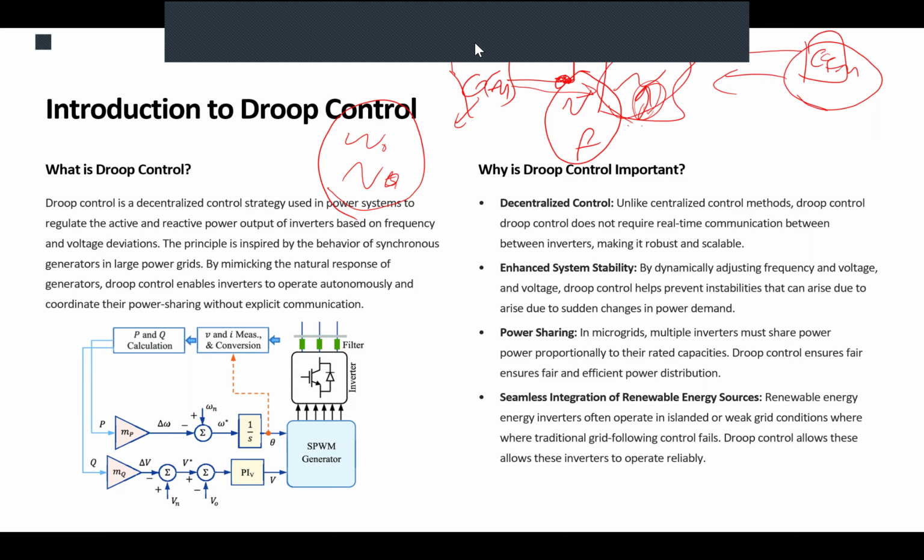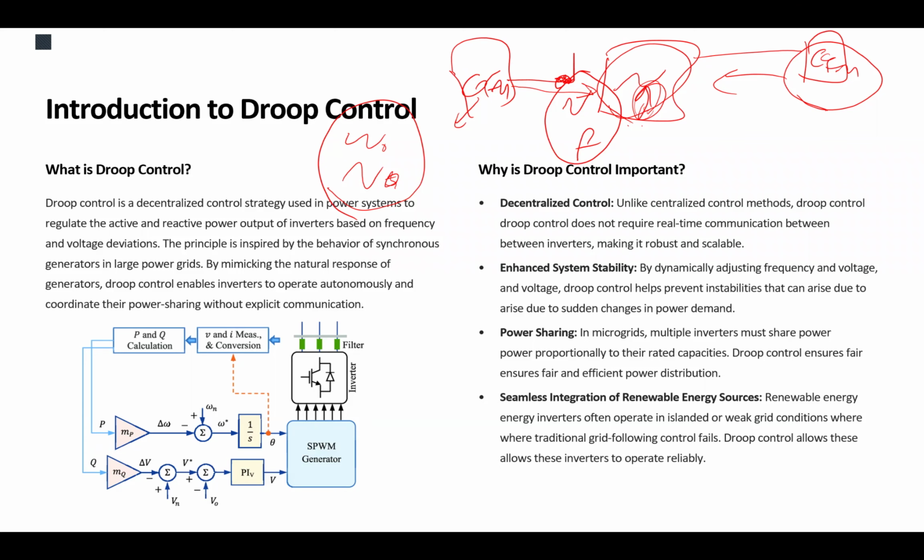No? Okay. Now, as we talked about when I wanted to answer Christine's question, another aspect of the group control is the power sharing. Because they all want to keep their own settings at the terminal, they are motivated to pick up the overload or underload situation in the grid. So without any communication with each other, they share whatever deviation happens in the grid to get rid of that deviation and stabilize the system again.